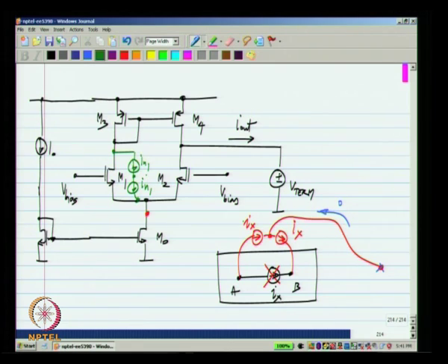Okay. Now, normally you are used to calculating noise from different sources and assuming they are uncorrelated. In this case they are perfectly correlated, because we are simply replicating the current, and we will connect the middle to ground and we will analyze the two separately. Now, we do not have to do further analysis because this IN1 is like the previous analysis we did with the noise current source of M3, and the lower IN1 is like the analysis we did with the noise current of M0.